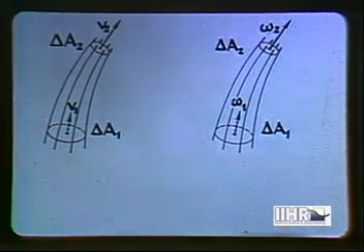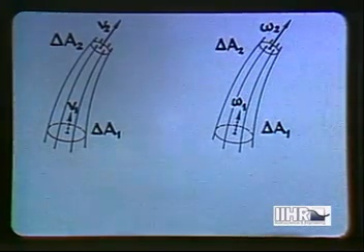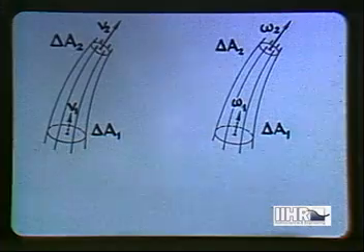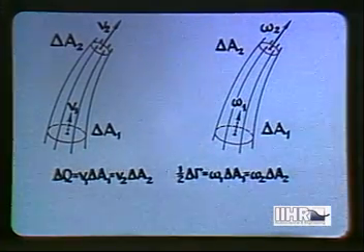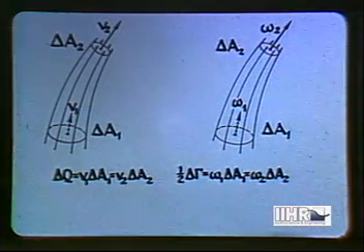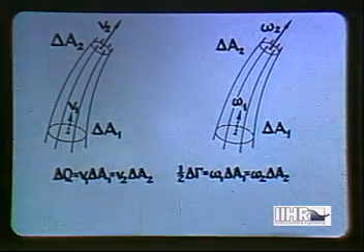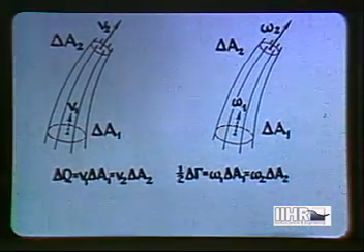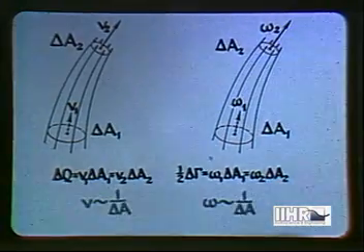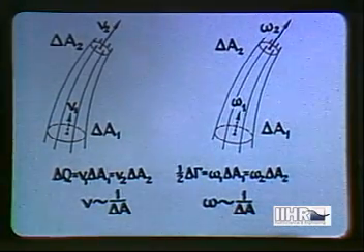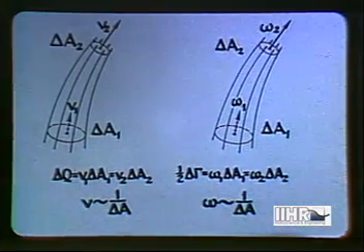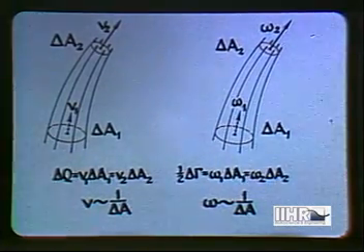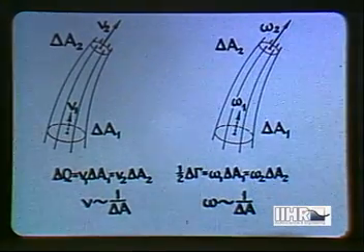Just as the product of the velocity and cross-sectional area of a stream filament is known as the rate of flow, q, the product of twice the vorticity and the cross-sectional area of a vortex filament is known as the circulation, gamma. A theorem of Helmholtz, like the continuity principle, states that the circulation must be the same at all sections of a vortex filament. The vorticity thus varies inversely with the area of the filament.